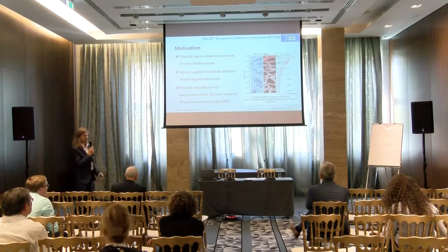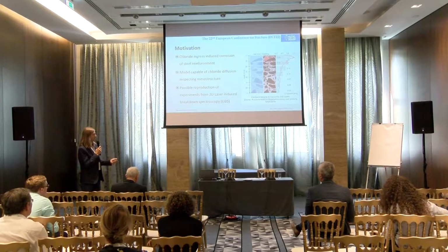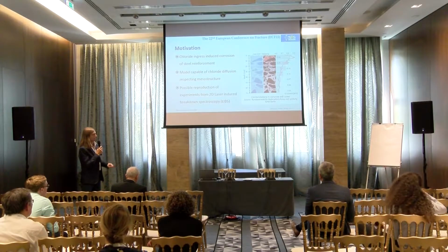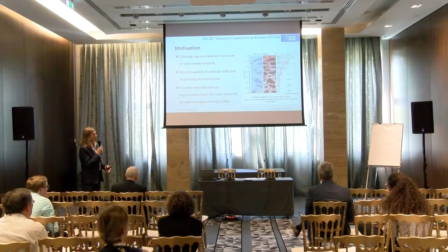And there are several approaches to analyze the effect of chlorides. And currently there is an availability to analyze even 2D profile of the chloride content in the concrete via laser-induced breakdown spectroscopy.